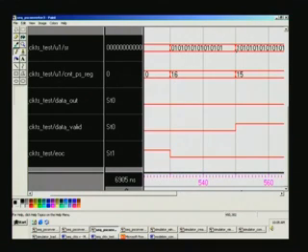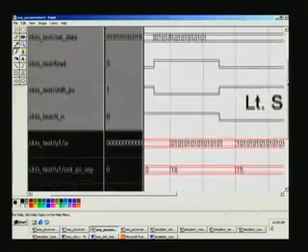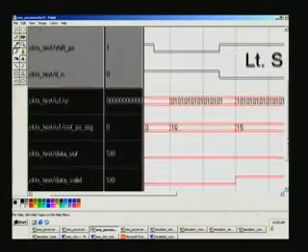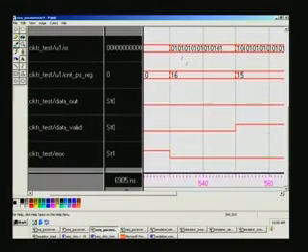And once again the parallel to serial conversion takes place, but this time it is left shift as is here. So, it was 1 here for the earlier thing, it becomes 0 here, implying it is a left shift. So, if it is left shift, 0 must go through first, that is data out is here.